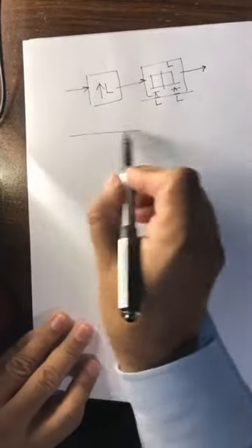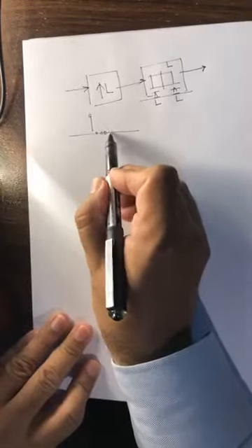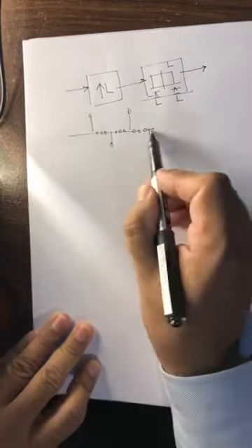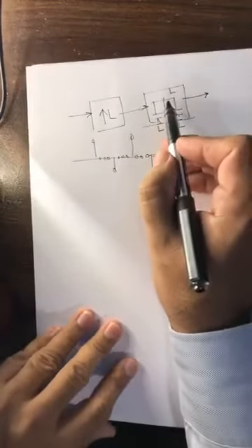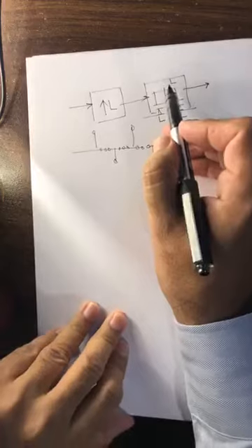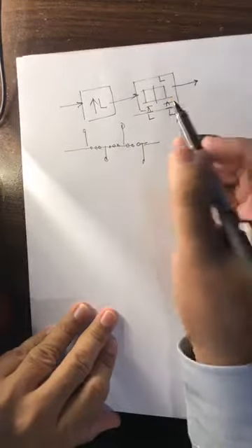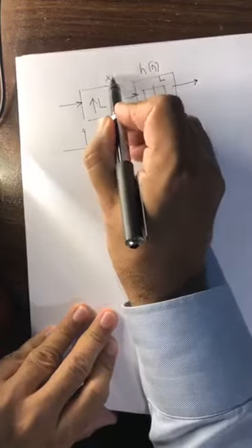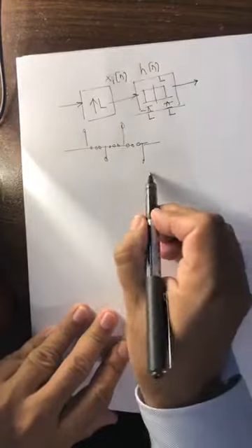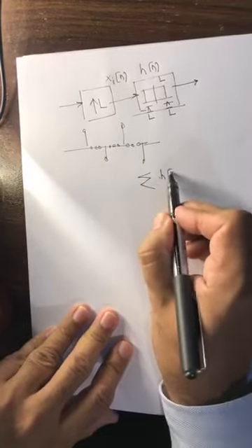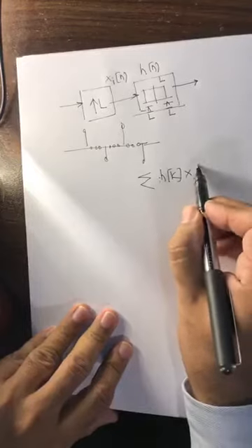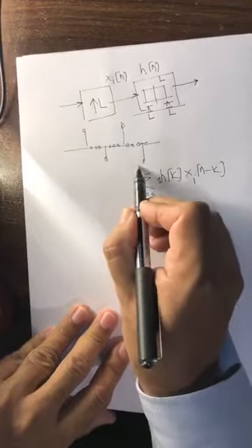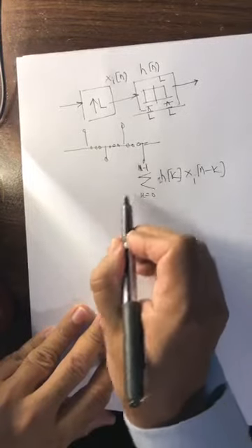And so you have a signal. Now you have 0, 0, then 0, 0, then 0, 0. Okay, and then passing it through a filter simply means a convolution. And convolution, again, you have a filter h of n, and this is the signal x interpolated of n, and convolving means you have h of k times x interpolated of n minus k, where k goes from 0 to M minus 1.